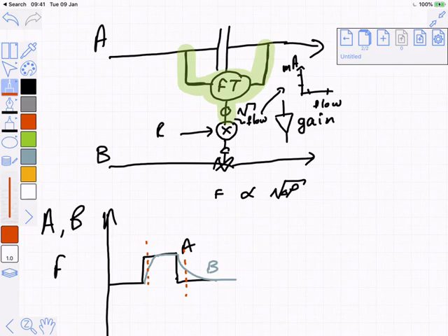I don't, in fact, in this scheme, even know what the flow rate of B is, because I'm not measuring. And so what does that mean? It means that the control will be significantly worse than I've sketched it over here. Now, what's the big take home of all of that? Is that you cannot rely on ratio controllers to obtain a ratio. Like if you rely on getting an actual exact ratio into your reactor, you cannot do it using ratio. Okay?